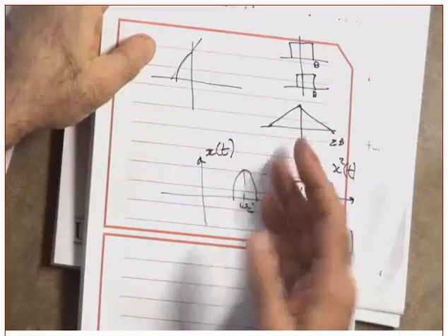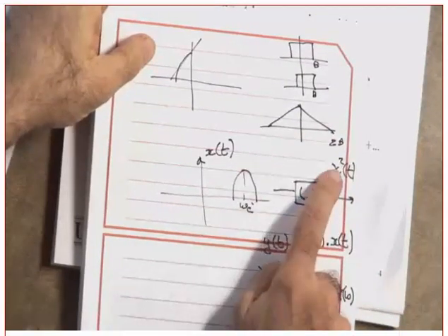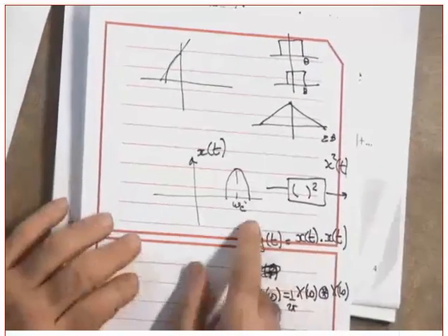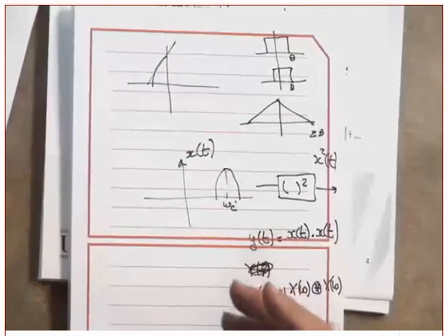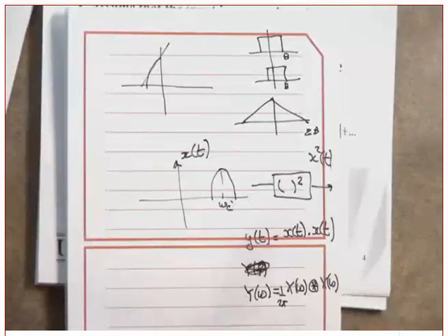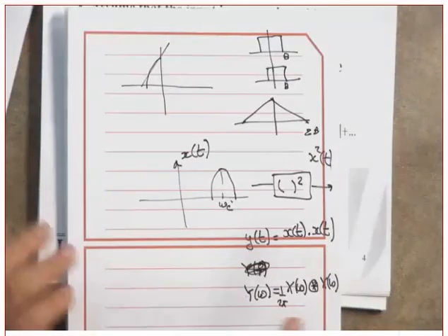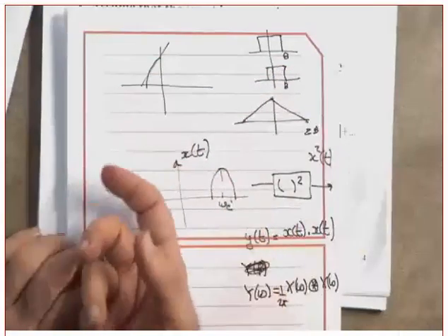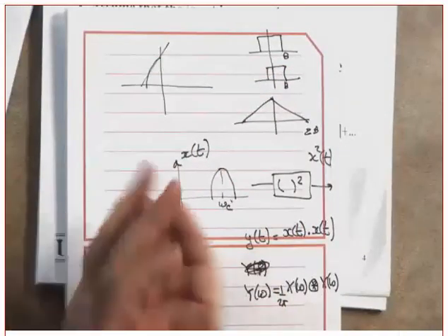And by the way, the more the nonlinearity is, the wider it is. Why? Because you are convolving again. Whenever you convolve, the bandwidth will increase. So if you do have, for example, raised to the power 3, what does it mean? With this one, you are going to convolve this with it again. Are you following or not? It will also increase. Did you get my point?